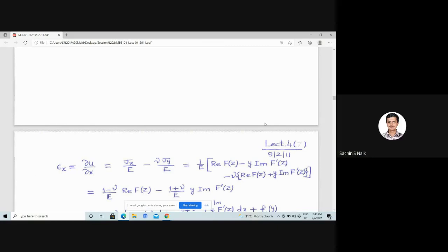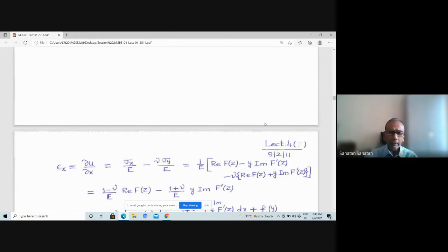Oh, so the Kolosov work is actually a general mathematical work, or it was in the direction of only fracture mechanics? That's my question. No, okay, that's a good question. The Kolosov-Muskhelishvili formulation was not referred to cracks. Yeah, that's what I wanted to confirm. Yeah, they actually tackled the problem of general stress analysis. That's why they define it in terms of 2 analytic functions, which makes it available for any application in 2-dimensional problems. You can have crack, no crack. But in the case of cracks, in general, there are certain simplifications possible, and that's what Westergaard looked into.